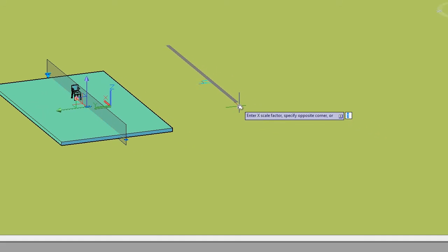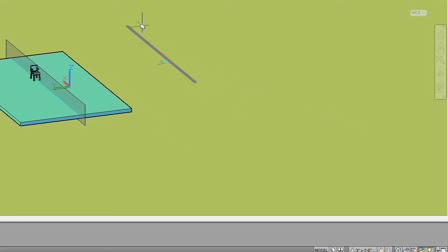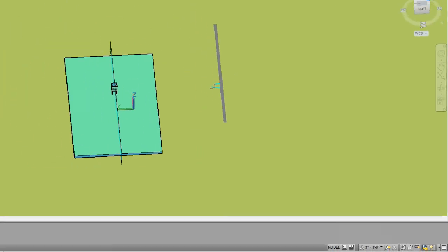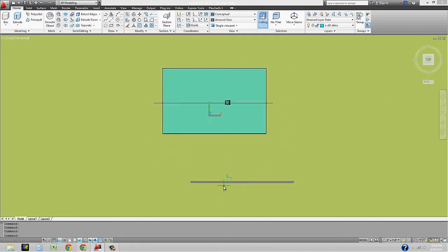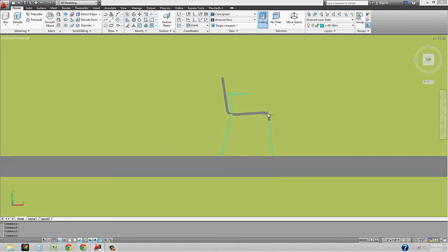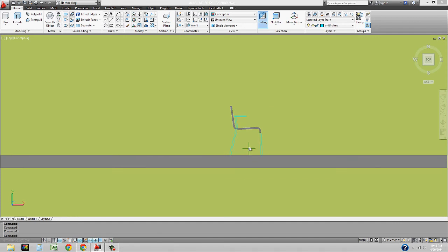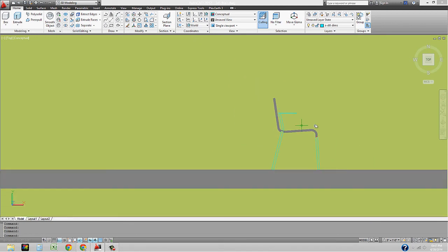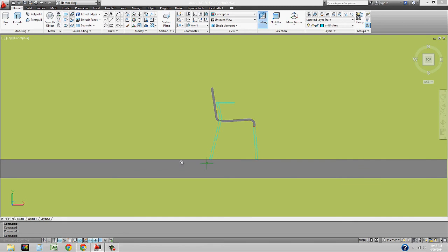And you'll see that now, if I click okay and hit enter, enter, and enter, and go to my top view, you'll see that it inserts this drawing as a flat two-dimensional drawing. And what's hatched is actually where it's taking the cut. And this is where people tend to have an issue if they built their model using planes, because there's technically no solid to cut through, so they might not see this hatch. Then they have to figure out where that section cut was cut through. But here, as a solid object, it actually shows you where it's taking that cut.